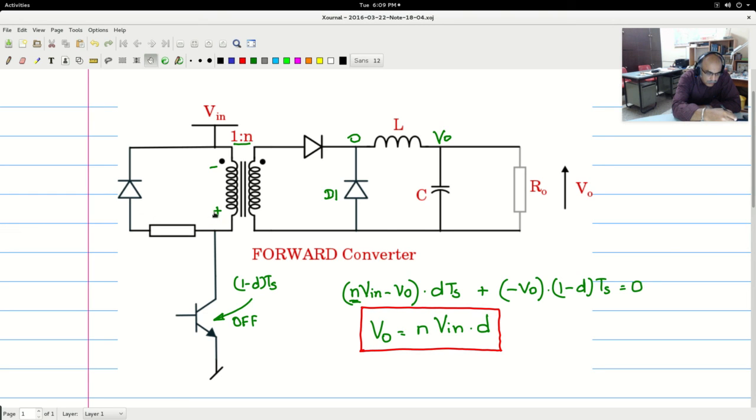Now the moment it is freewheeling, let us say the diode is ideal, there is an L in the primary, the magnetizing inductance, and this resistance R. So in an L by R ratio, there will be a current which will be decaying. So it will be decaying with the L by R time constant exponentially. So exponentially the flux will decay.